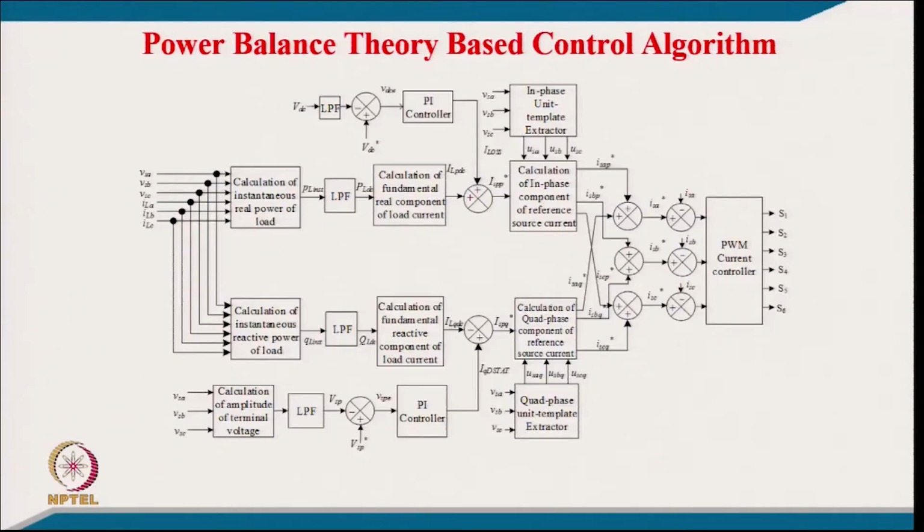So, this control algorithm will certainly reduce the burden on both PI controllers, for voltage regulation as well as for power factor correction. Here, of course, we can discuss what we are sensing. We are sensing the 3-phase voltage, maybe line voltage, because phase voltage in a 3-wire system is not available, and then we have 3-phase load current estimation.